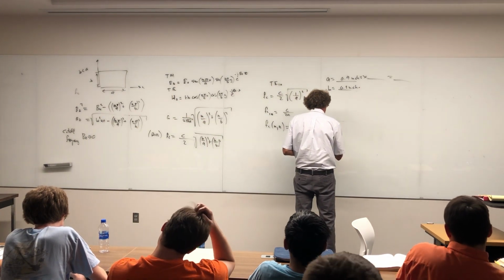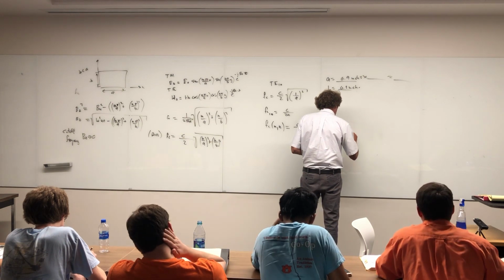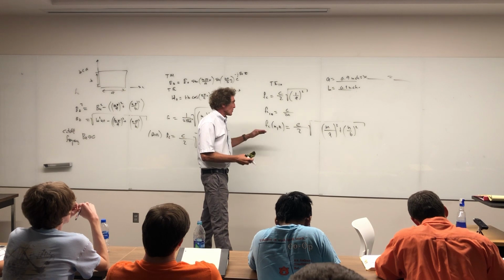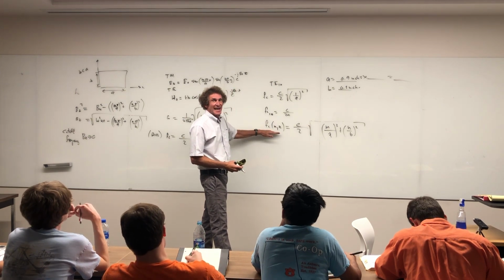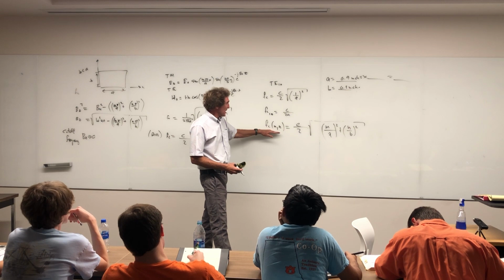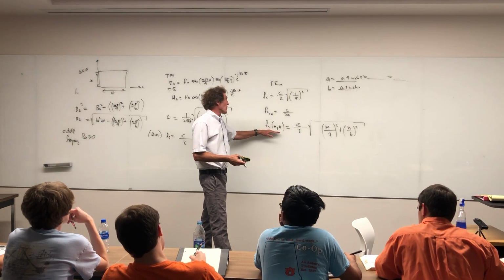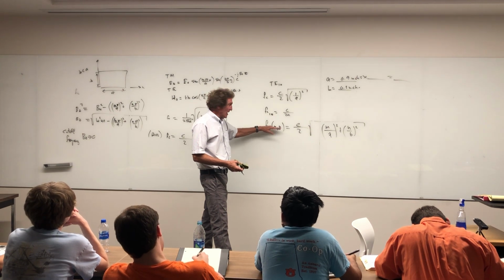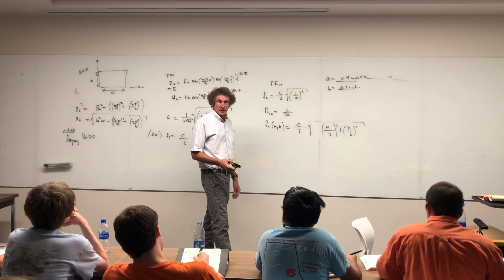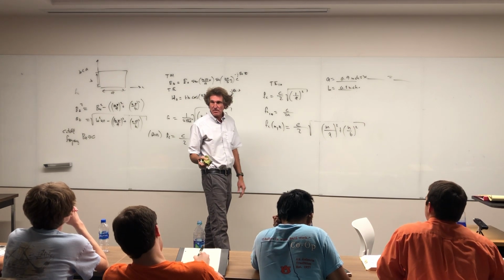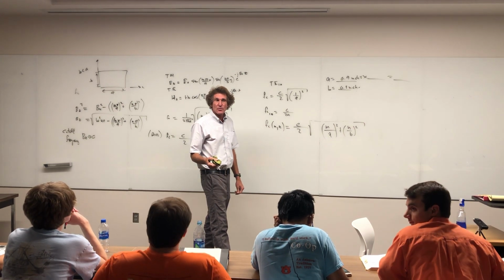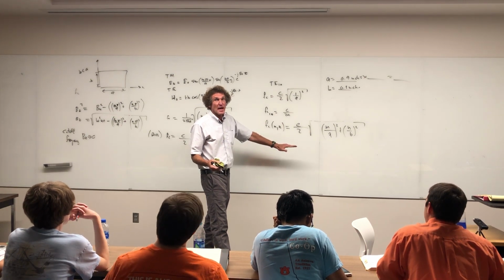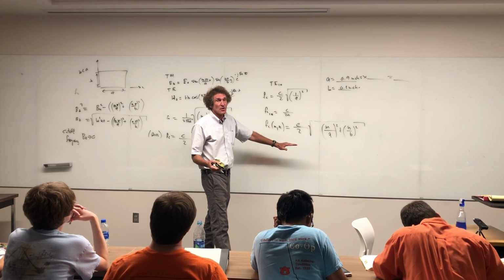This is M over A squared plus N over B squared. So when you do this, and you can do this in MATLAB in a heartbeat, you write this equation down, you put in the value of A in inches and B in inches, and then you just say, for M equals 1 to 3, for N equals 1 to 3, find this, and then print this. And you'll see, did anybody do this one in here? If you do it, what you're going to see is very predictable. 1-0, 2-0, and then 3-0 will be 0-1. There'll be what's called a double mode.